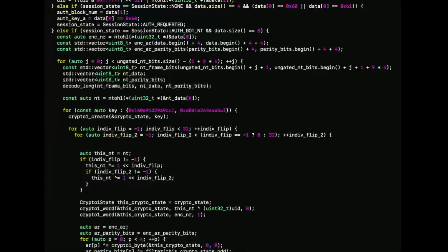The reader normally has to say, I want to authenticate, okay, blah, blah, blah. I want this block, okay, what's your CSN, blah, blah, blah. All these messages, we don't care about that. All we want to see is the magic 8 bytes in a transaction. So we only care about the two nonces that the reader and the card give, and the block request from the reader and a response from the card.